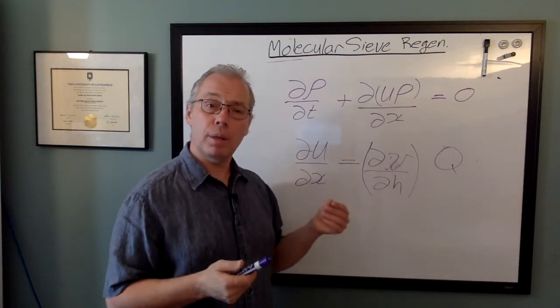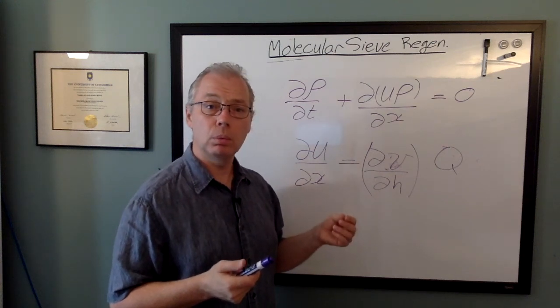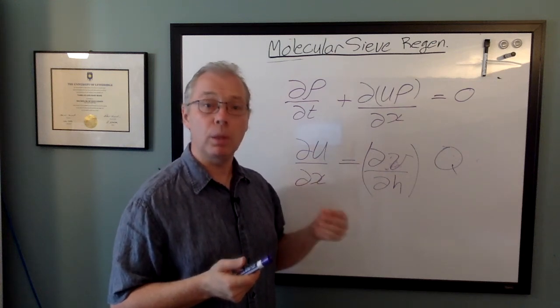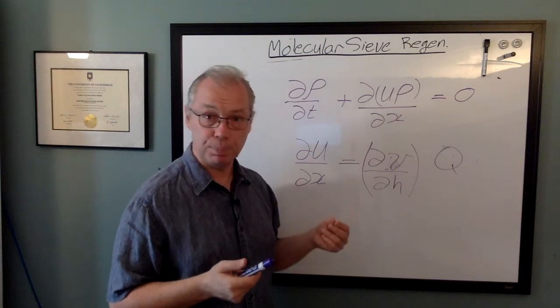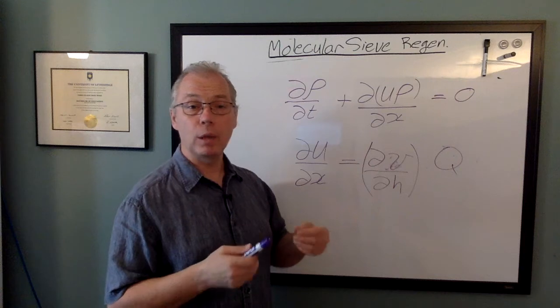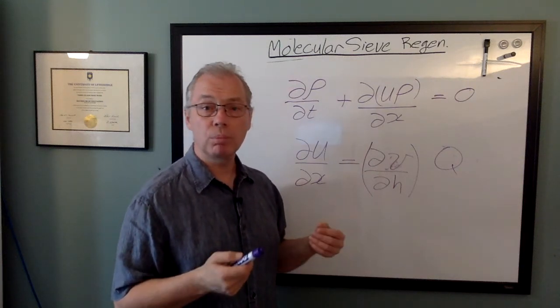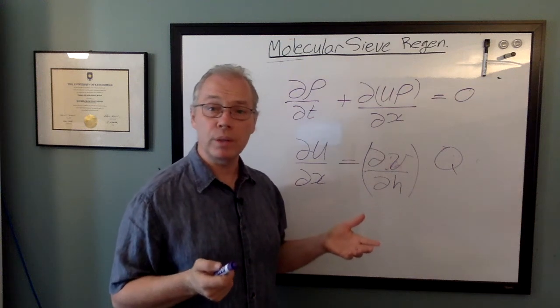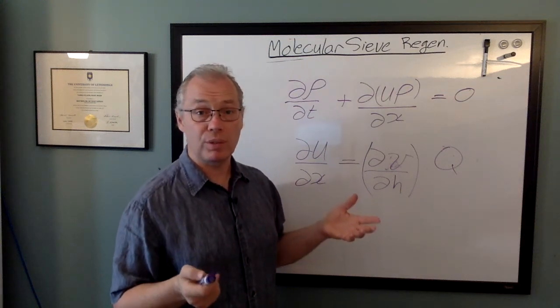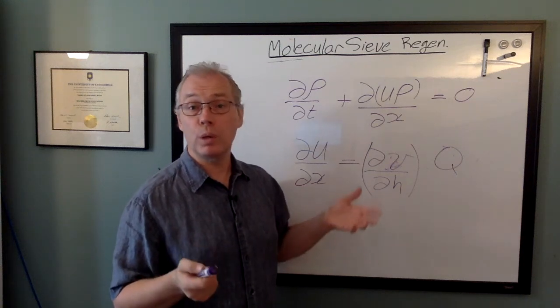The other result that we're interested in is the outlet mass flow and how this evolves over time. This is what is delivered to the next unit operation. And just for reference, the process operates at 2000 kPa, the furnace feed is at 40 degrees Celsius, the bubble temperature is 57 Celsius. Eventually, the furnace outlet temperature is going to be 210 C.